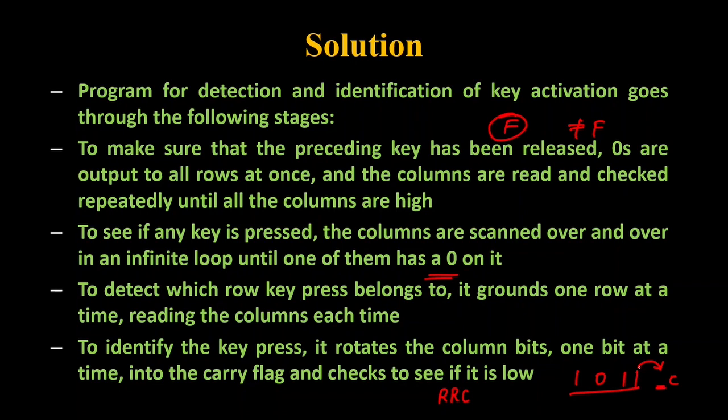If you get your carry bit here, what is the value I can get here? It is going to be 0101, right? So your carry bit is going to get the value of 1. Again, rotate right with carry. What is the value I am going to get here again? In the next iteration, it is going to be 0010 and the carry bit will be 1 again. So this is going to take the next position, right? Again, if I rotate right, what value am I going to get?